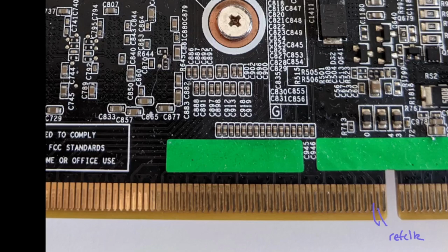of repair. For this particular card, the numbering for the capacitors for the differential pairs are 15, 14, 13, 12, 11, 10, 9, 8, and then 7 down to 0. And to reroute the traces, we would first need to do 15 down to lane 0, like so, and then 14 to lane 1, 13 to lane 2, and then 12 to lane 3.